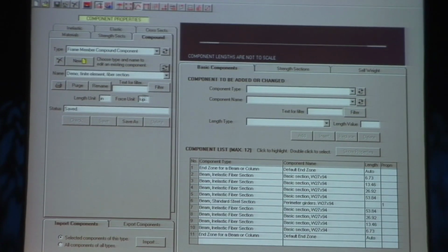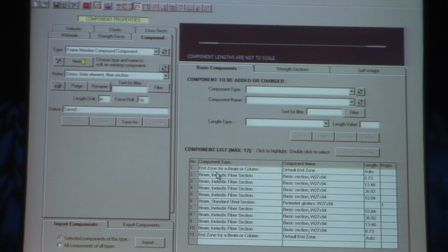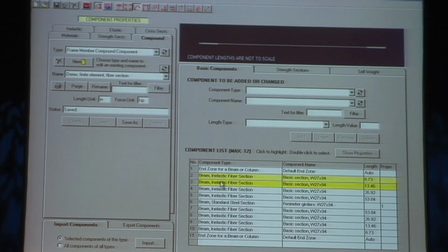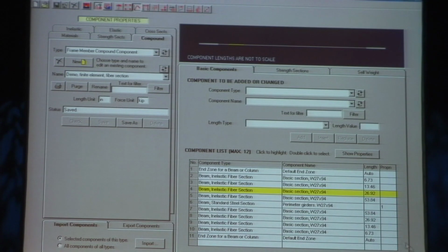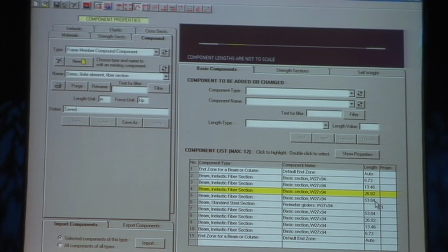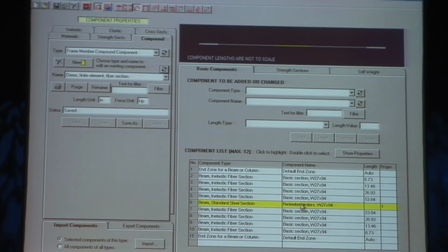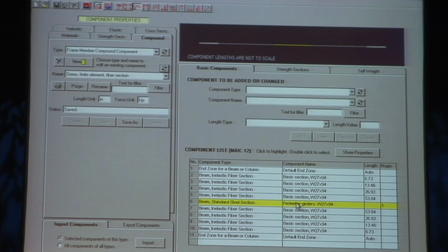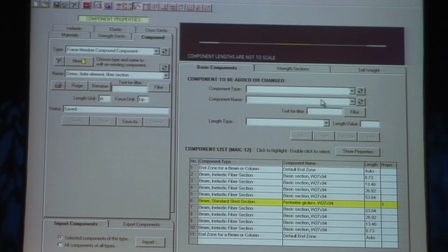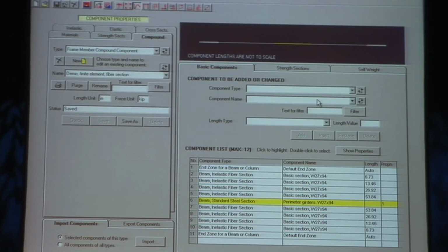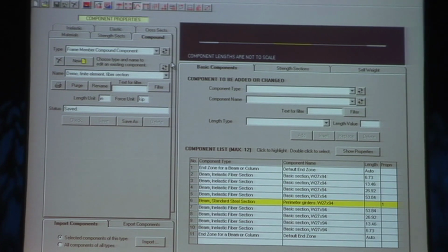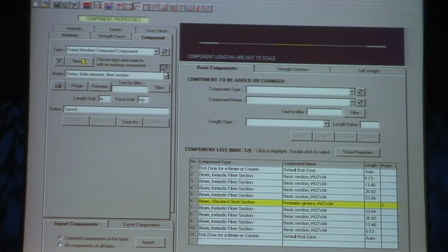The next one would be a finite element model, again using the same fiber section, end zone, and then some finite elements of different lengths, 6 inches, 13.5 inches, 27 inches, and 54 inches, and then the elastic beam in the middle is whatever is left. I don't know what the span is presently, so the elastic beam in the middle would be whatever is left. This would be a finite element model.